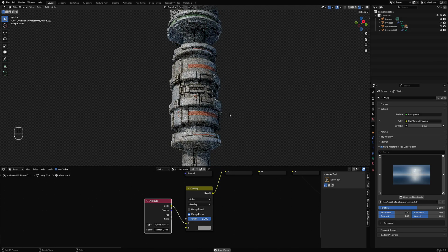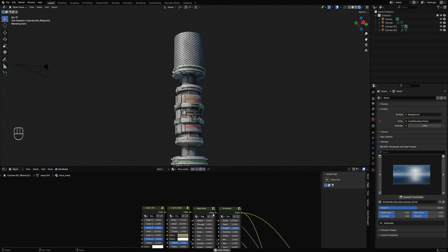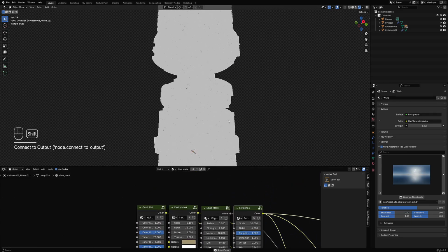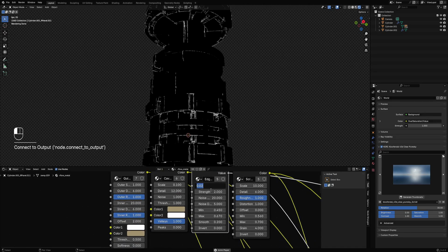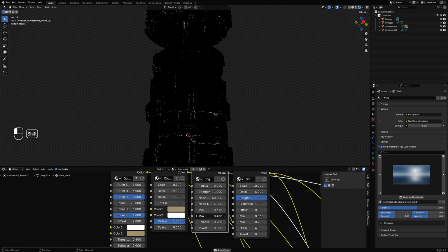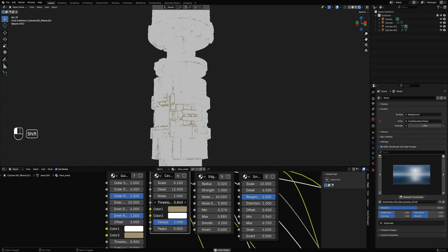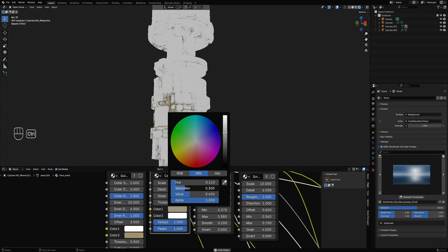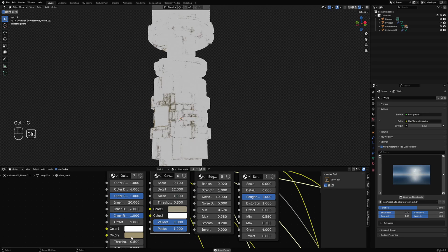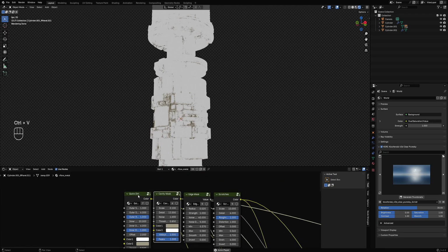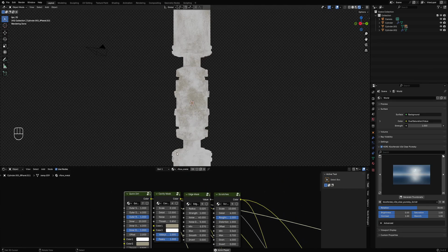And then when you use the second color bar, you can control the intensity or the value of the vertex color. Okay, so we have something like this, and then we need to modify the rest of the shader groups. So this one, something like 1, and make the noise smaller by using a higher value. Cavity, this is our cavity threshold, decrease the threshold. Let's try and use peaks and use something like saturation 0.3. Copy this to the quick dirt, and let's view the quick dirt. Still good.